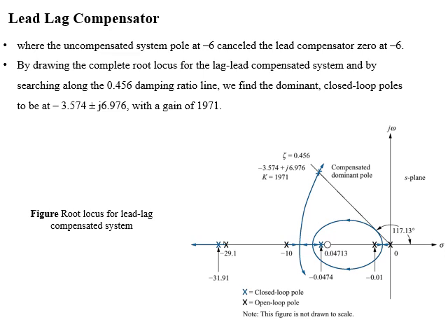Dear students, the figure represents the root locus for the lag-lead compensated system, where the uncompensated system pole is cancelled by a lead compensator zero at minus 6.